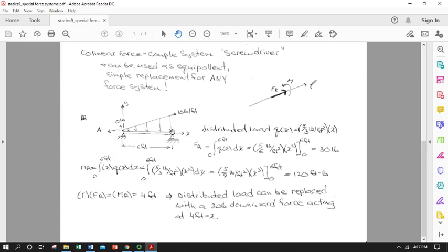And we have a distributed load, usually denoted by Q, which is a function of where you are on the beam. So this could be maybe like a tank or a container of gravel where the pile is really high over at this point, and there's none over here. It's an uneven load, and so the weight of that, the pounds per linear foot, is much higher here than it is over here.